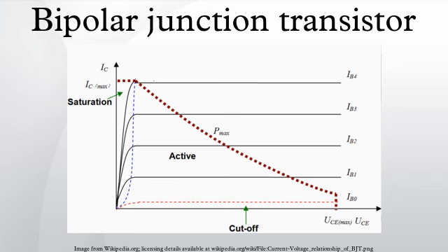The common emitter current gain is represented by βF or hFE. It is approximately the ratio of the DC collector current to the DC base current in forward active region. It is typically greater than 100 for small signal transistors but can be smaller in transistors designed for high power applications. Another important parameter is the common base current gain, αF.